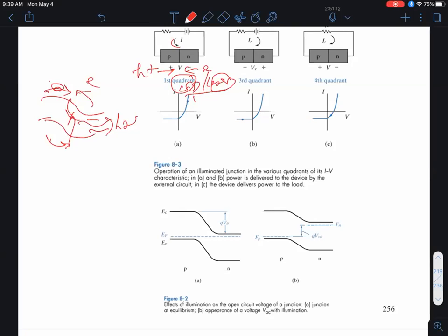All right. Now, if I operate in quadrant, so that's quadrant 1. Quadrant 2, there's nothing that happens over there. That's quadrant 3, and that's quadrant 4. So in quadrant 3, I end up getting basically a leakage current that's proportional to the photon flux. And that's what I use in a so-called photo detector or photodiode. Okay. I'll hopefully get to that at the end of this class, or maybe on Wednesday.